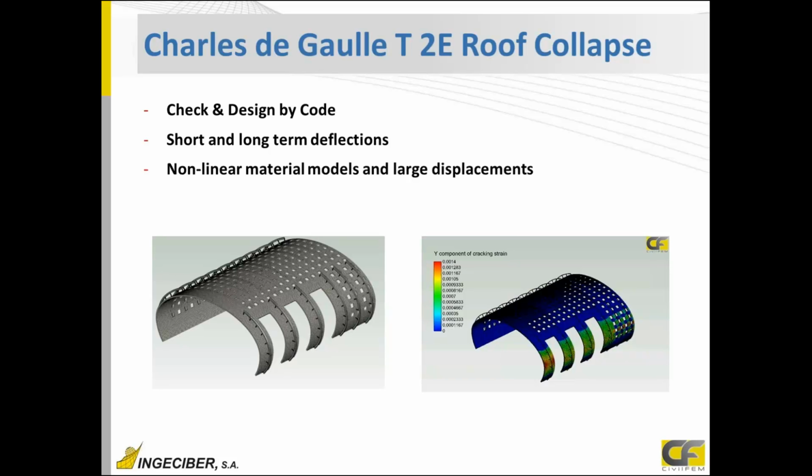First with shell elements. In shell elements we can add nonlinear behavior to compute short and long-term deflections. We will also control the deflections, and finally adding more nonlinearities like material nonlinearities and large displacements.